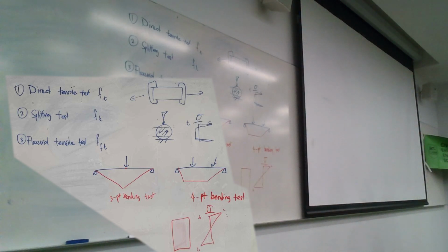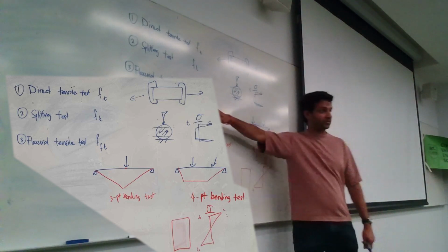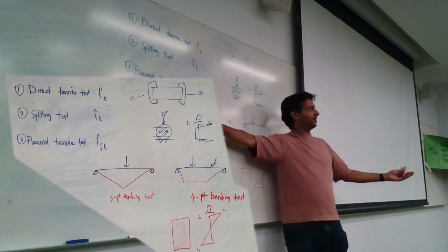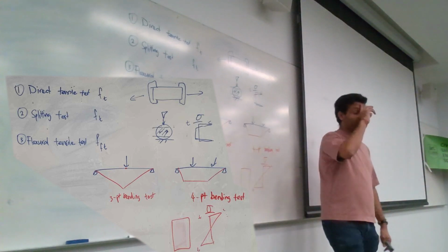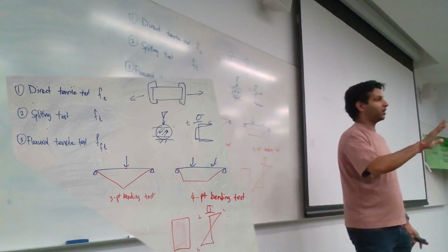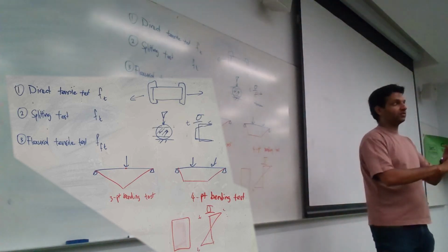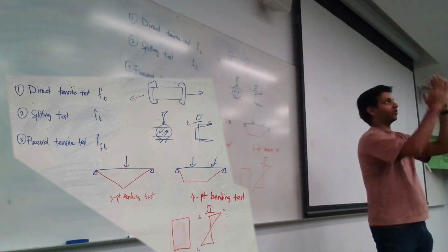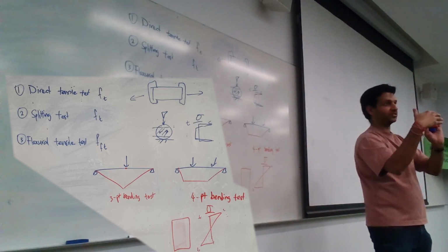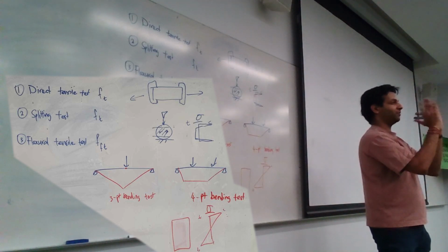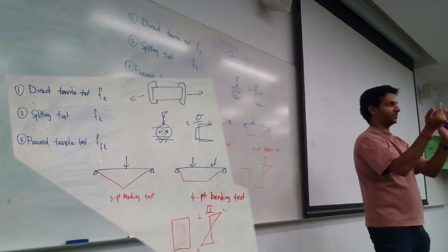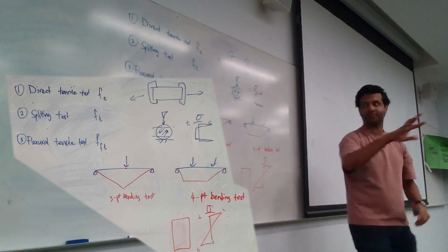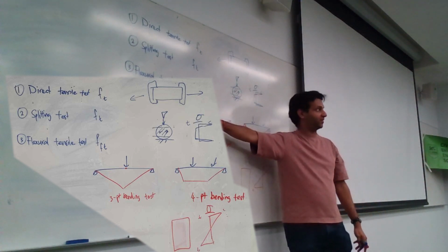Exactly. It's because we got this test result through beam bending. It's the most applicable, right? So just be careful when you're doing column design even. If you've got a long column and the column is going to buckle and snap on the tension side, when something buckles, it basically behaves like a beam. It'll bend like that. You'll have a compression side, you'll have a tension side. When the tension side splits, it's basically beam behavior.